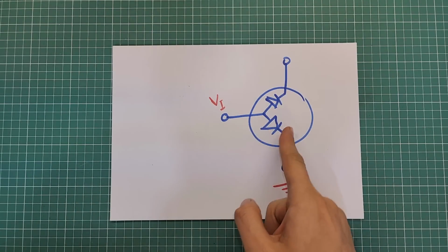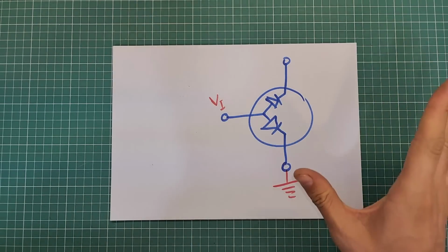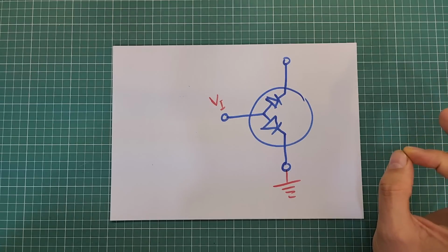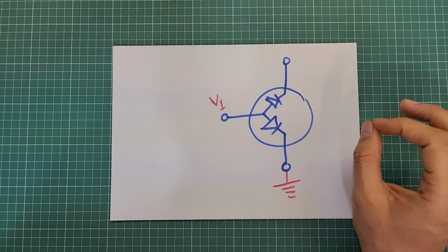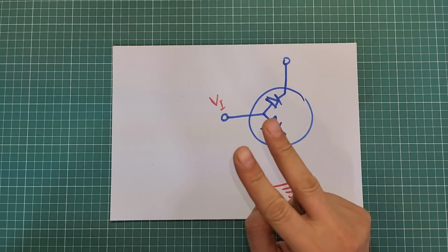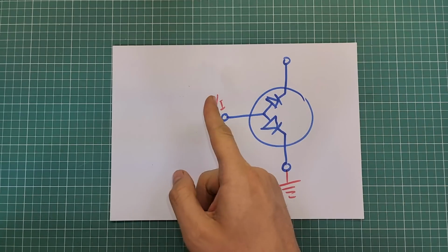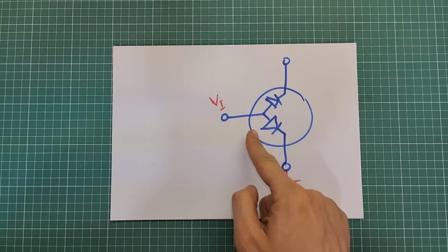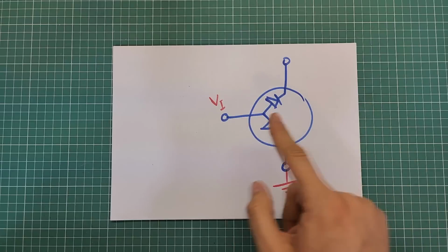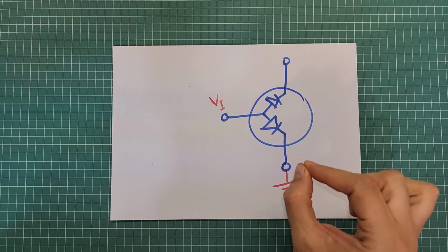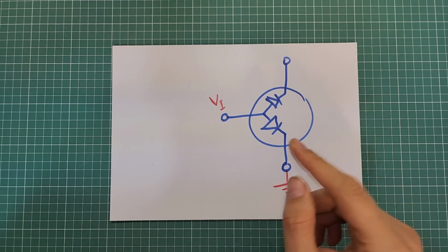If the diode inside the transistor is directly connected to a voltage source without any resistance between them, one of these consequences will follow. 1. The transistor will be destroyed. 2. The voltage source will be destroyed. If the voltage source is strong enough, it will destroy this diode and eventually the transistor by delivering high current to this junction. And if the voltage source is not strong enough to deliver much current, the voltage source itself